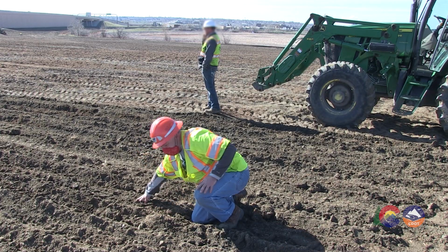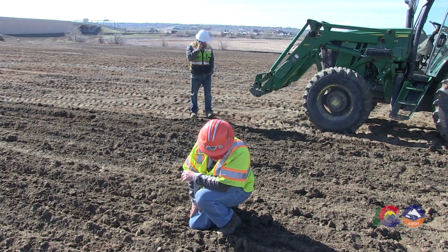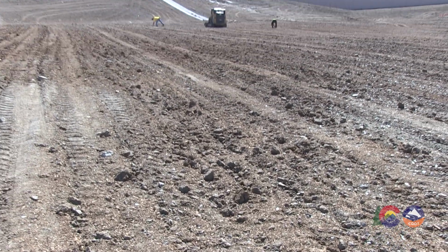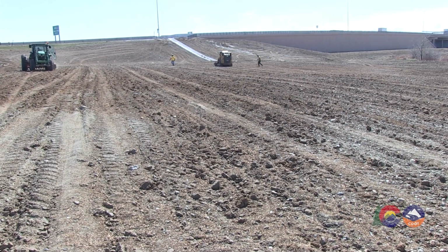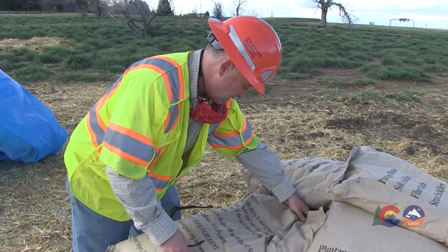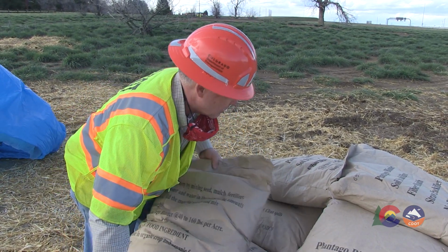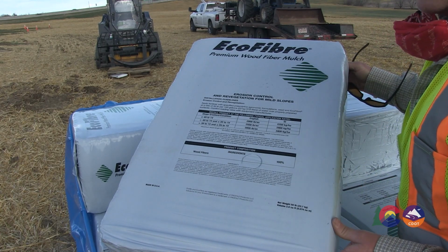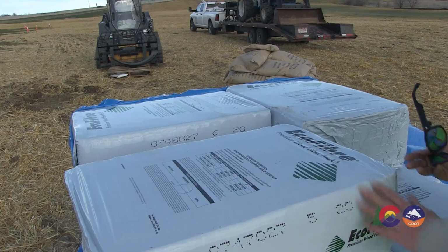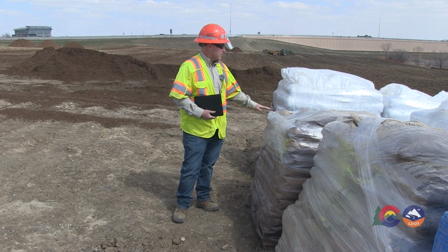Guidance and checklists are available on the CDOT Landscape Architecture website. Contractor submittals must meet the 212 specifications. There is a checklist in the Construction Bulletin for assistance. Always check the bag label for compliance with respect to mixture type, pellet or granular, low or high nitrogen percent nutrients, and class. No open, damaged, or unlabeled bags or containers will be accepted.